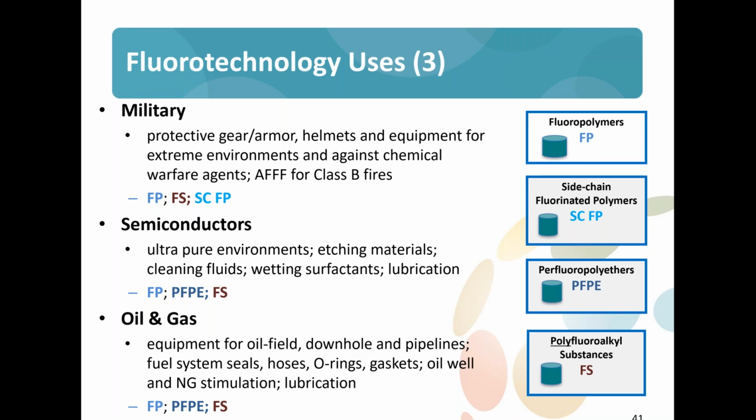Semiconductor environment: an incredible need for ultra pure environments, and the fluoropolymers, the perfluoropolyethers, and the fluorosurfactants provide the ability to create those environments, to create etching materials, to create cleaning fluids for surfactants, and lubrication. The perfluoropolyether oils in particular are used in many of the pumps that are used in those high-end semiconductor systems.